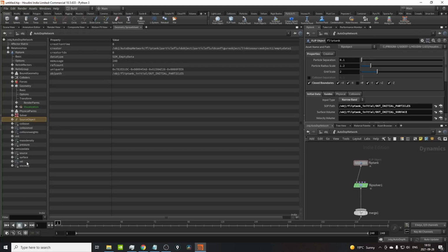So if all of these are super high res, your simulation is going to take ages, right? So Houdini by default said, hey, let's just simulate our volumes at double the resolution than what the user wants the final resolution to be. And because we project everything back to points, we can just have more points than voxels, filling in these gaps, giving that additional breakup, giving that additional detail, making things look like they're very high resolution with less costs up front.